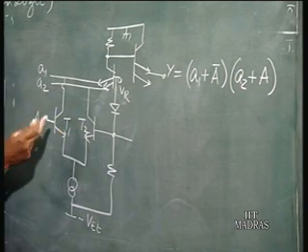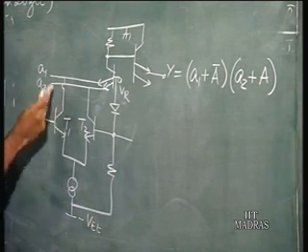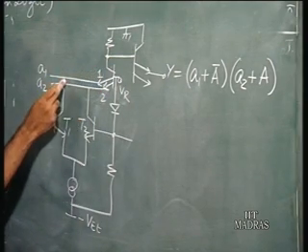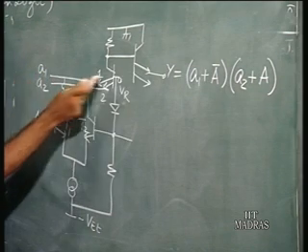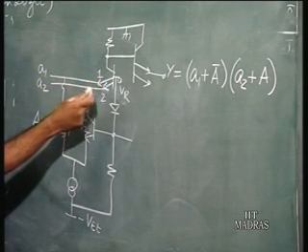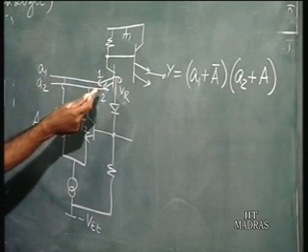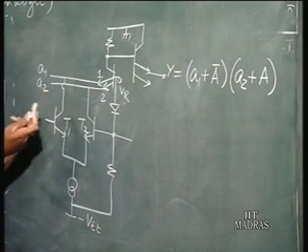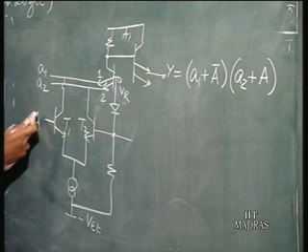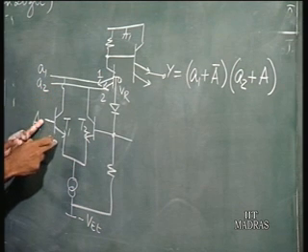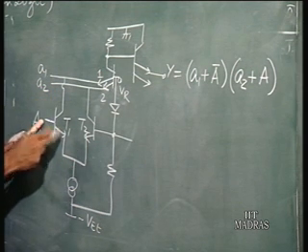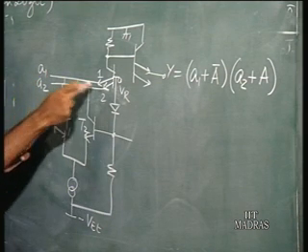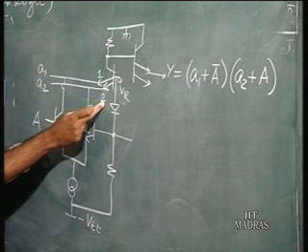Okay. So, I want to repeat, if you call this emitter 1 and emitter 2, emitter 1 is not going to conduct if A1 is high, which means it just switches off this emitter, because that emitter is not going to get forward biased sufficiently. Or even if A1 is low, if A is low, then there is no current flowing here, there is no path for the current to flow. So, if either A1 is high or A is low,